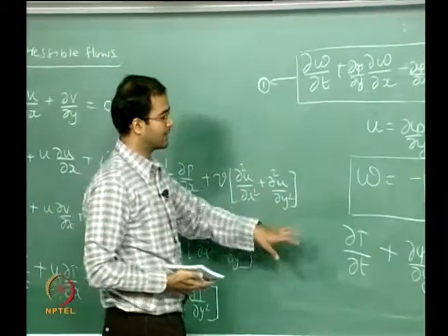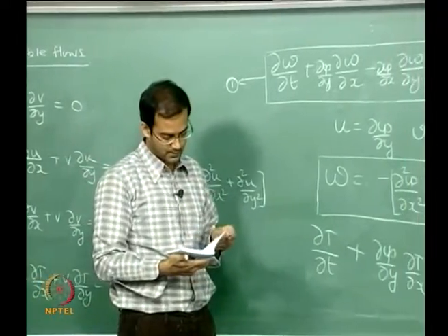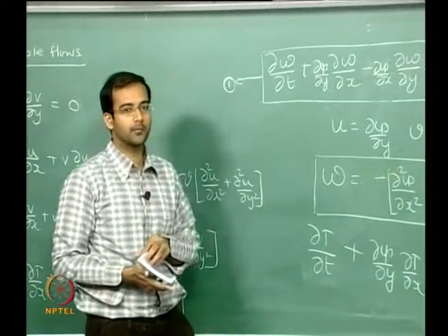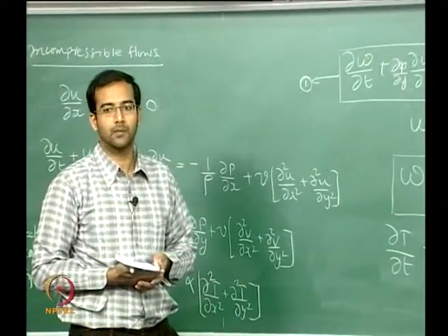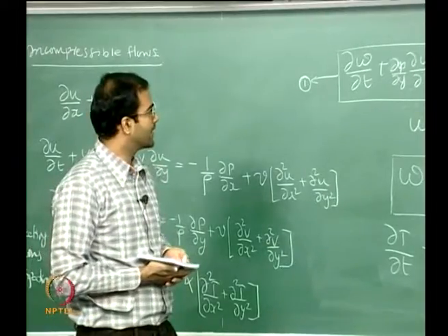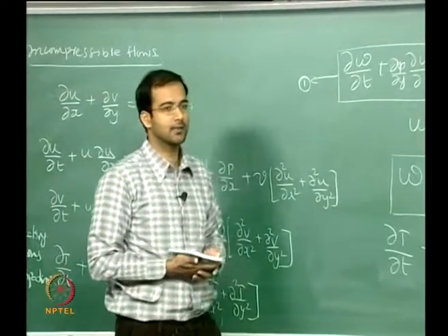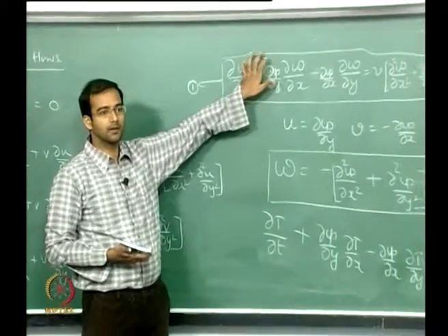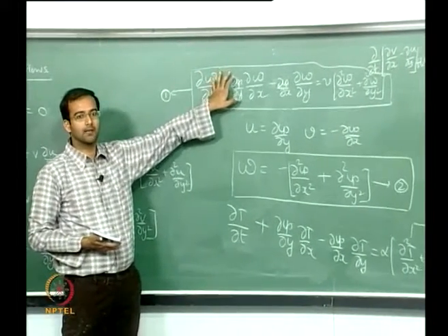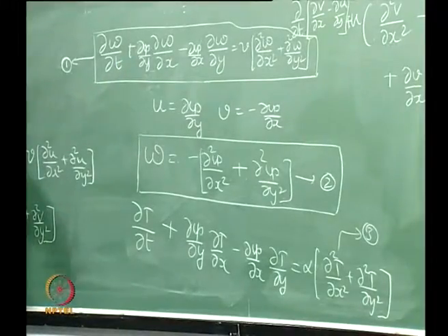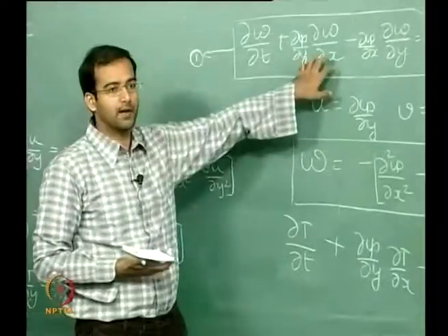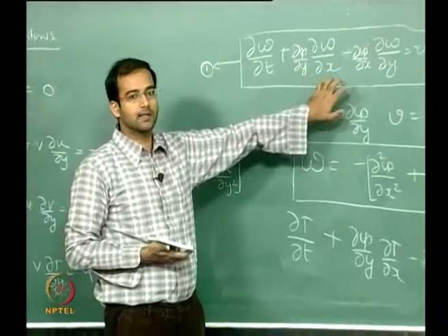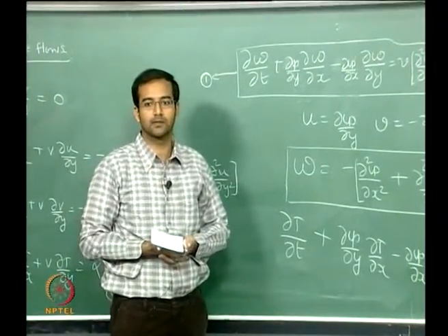So these are the equations that you exactly have to solve in your particular project, and I will be giving the papers. You have to apply the corresponding boundary conditions to solve this problem. For a particular problem you can look at the steady state solution, where you don't have to consider the time derivative, only the spatial derivative, and you can do this iteratively. There are a couple of techniques like Gauss-Seidel or Gauss-Jacobi iterative techniques, and you can use simple finite difference methods to discretize these derivative terms, alright.